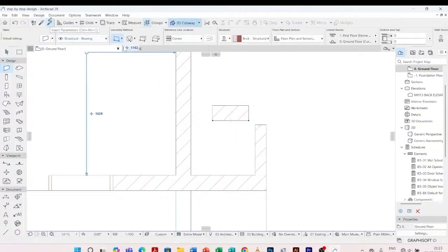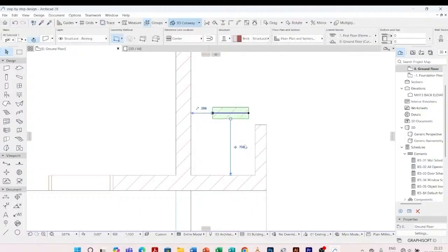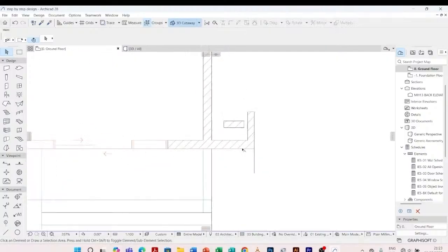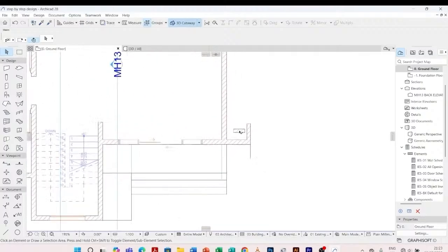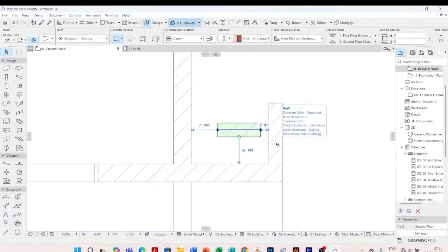I come and I inject it in this one. So that means this is also 150. So I'll give it a distance, or the duct width, I'll give it 300. I'll go with 300. Yeah, since I'm going to have a lot of ducts, I can give it 300.